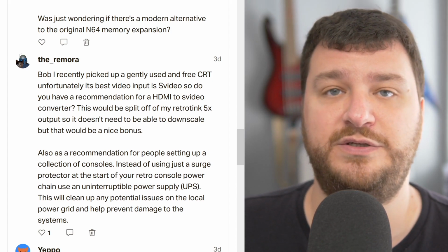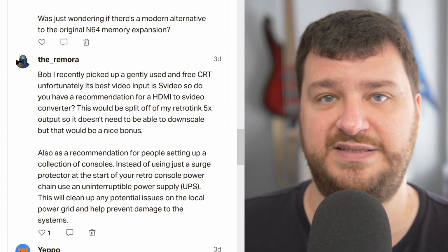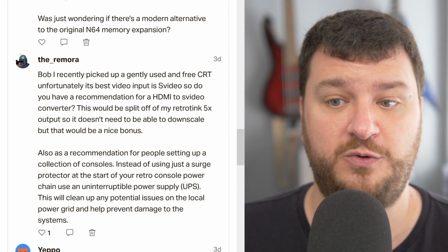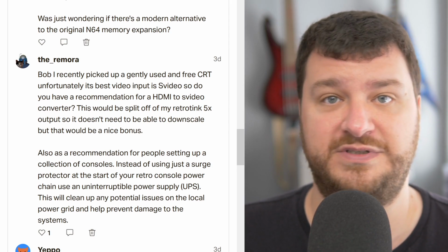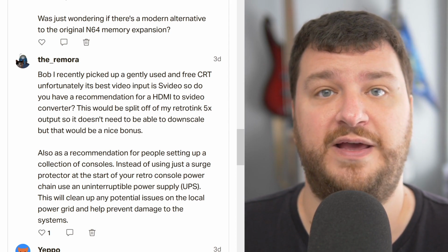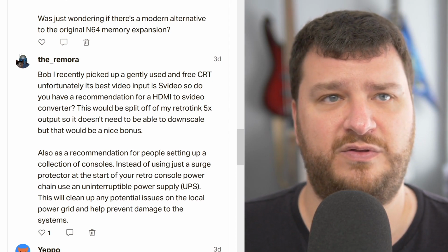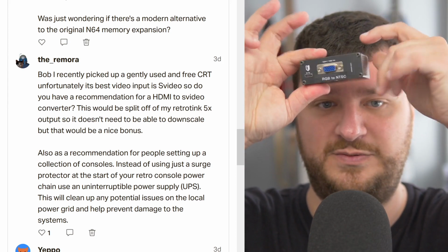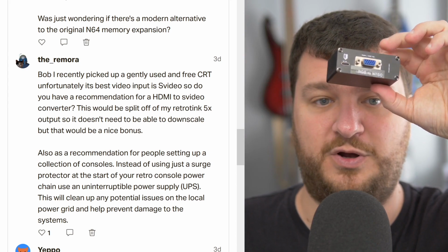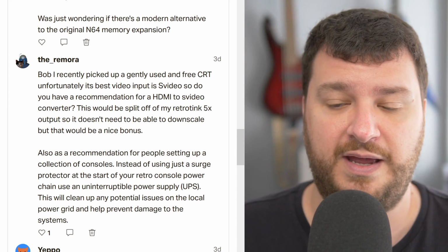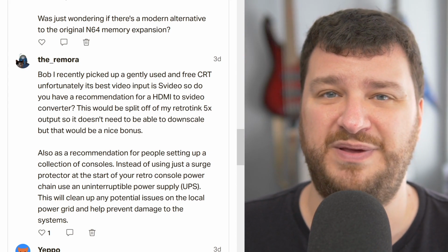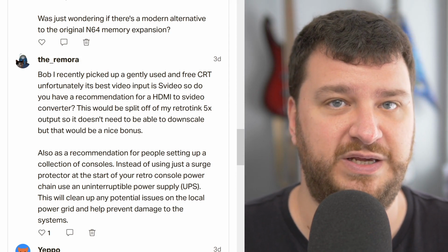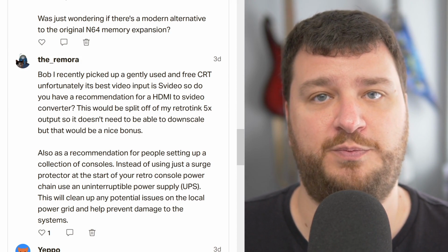So what you would need to do in that scenario would be to split that signal before it hits the RetroTink 5X. And lucky for you, because it's S-Video, there's converters out there now that are already available that could do this. So the AshenWorks one, the one from LinuxBot 3000, I happen to have that sitting right next to me here. These should all accept RGB signals in order to do that. Component to S-Video might be a different kind of conversion, and it might actually be easiest to go component to RGB to S-Video, but that should work perfectly fine.